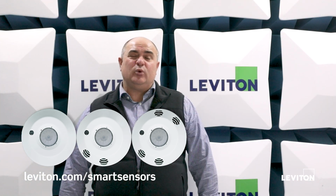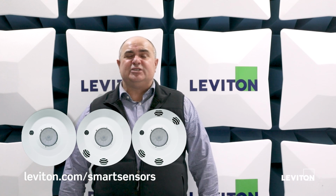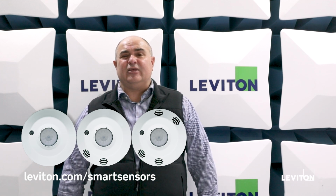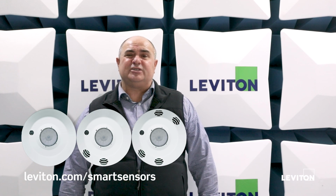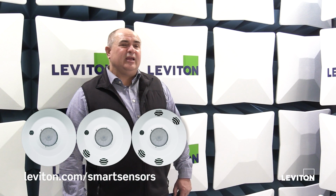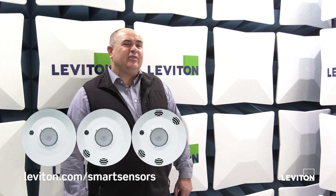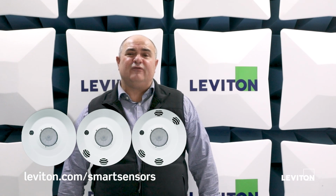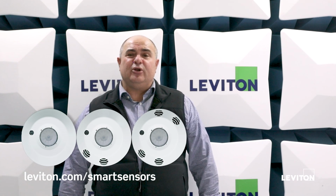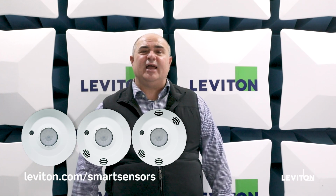However, in most applications, we have seen that the smart room controller, as well as the ceiling mounted sensor, are installed and operate in the closed loop manner for daylight harvesting. With closed loop, it uses the light pipe to actually measure the combined luminance of the natural light coming in, as well as the artificial light that's being provided by the fixtures within the space. The sensor can then adjust the light levels of the fixtures within the space, where it's merely supplementing the light that is required within the room based on the natural light that is coming in.